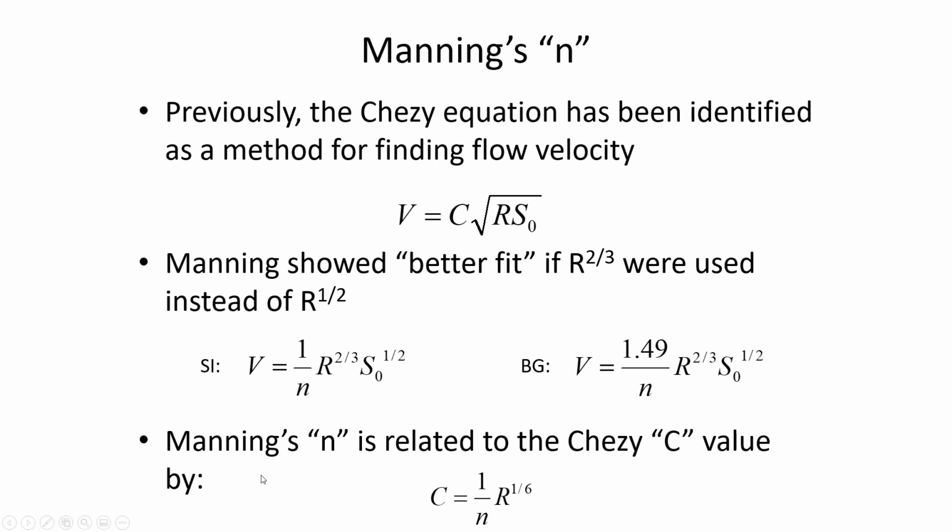All right. Manning's equation is used to characterize the effect of that shear stress, so the resistance to flow. My favorite, and your favorite, I hope, method of calculating resistance to flow when it was pipe flow was Darcy-Weisbach. And it's our favorite because it's so accurate. Maybe if you're thinking in terms of simplicity, then Hazen-Williams comes out on top, but it's not as accurate. Well, we don't have to choose. In open channel flow, we just effectively always go with Manning's equation.